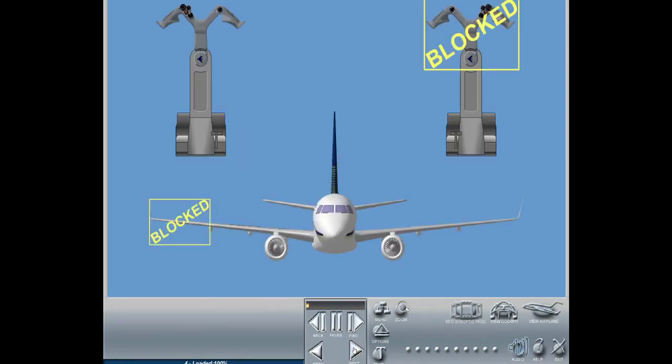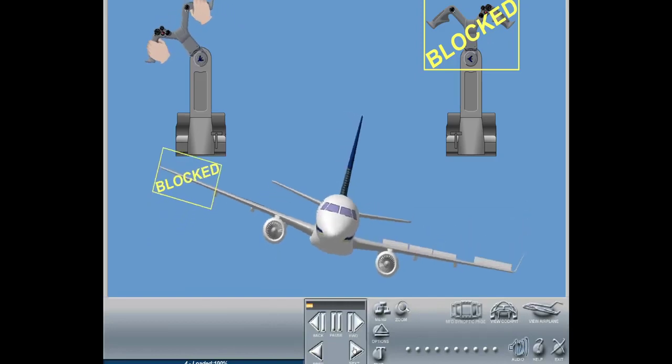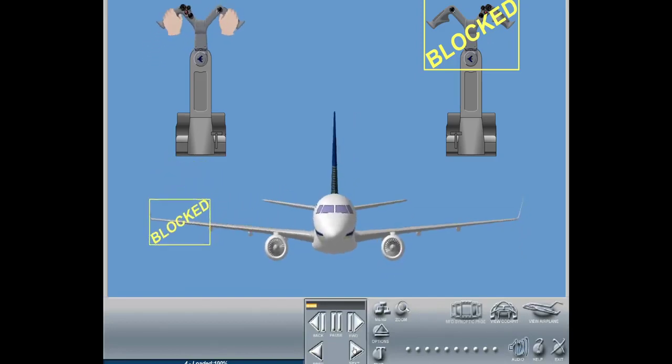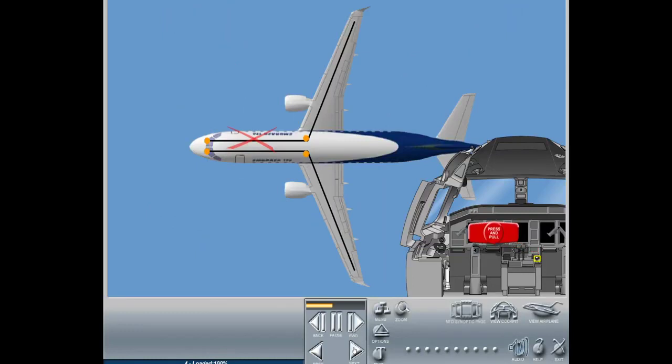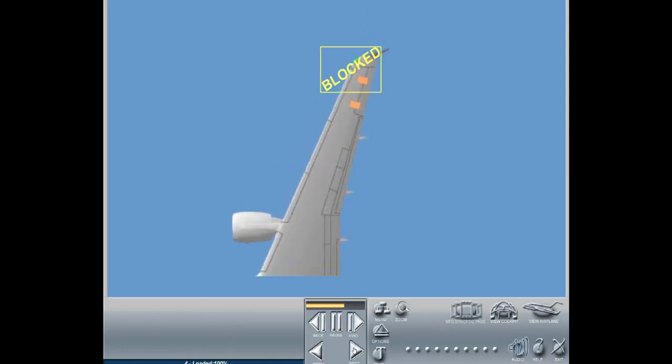Any single jam of the mechanical components of the system will leave half of the system operational. In case of a jam in either pilot's control wheel or the associated cable assembly, the pilot is able to control the aircraft using the non-jammed control wheel by operating the wheel disconnect unit to separate the two halves of the system. In the event of a jammed PCU actuator, the respective aileron surface will be hydraulically locked at the current position, and the pilot will retain control of the remaining aileron and all the roll spoilers by means of the jam override device.